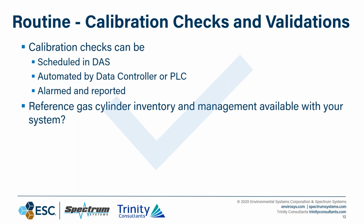That's a good point. I know that in the beginning, everybody starts off with just an automated daily cal. In an ideal world, it goes off at the same time every day. But in this day and age, your black box should be able to detect a first fire of the unit and, within a set amount of time, start a cal so you can protect your data.